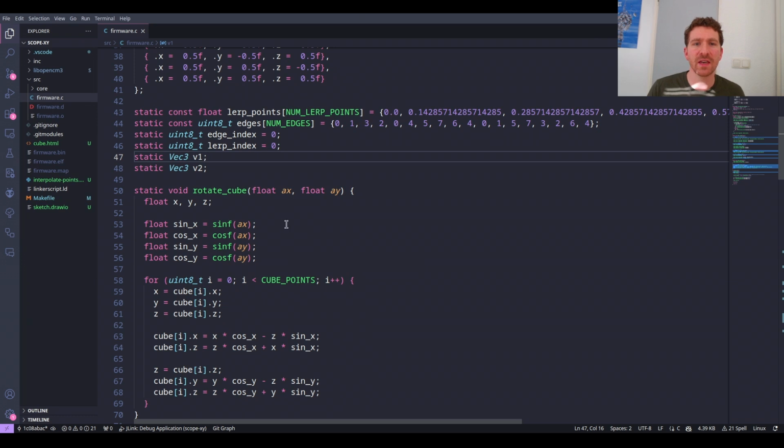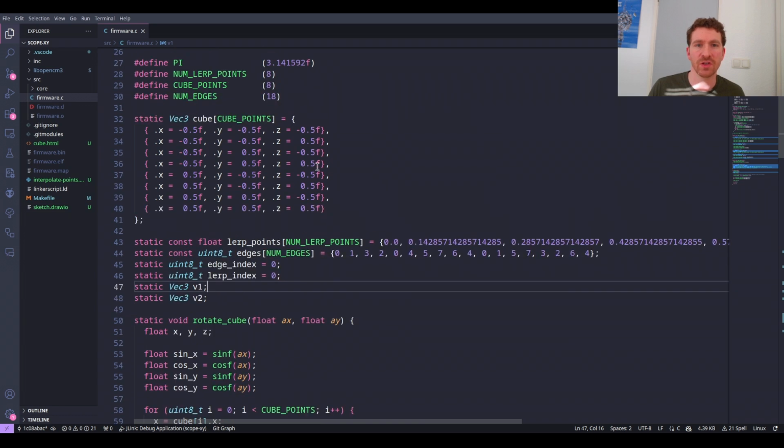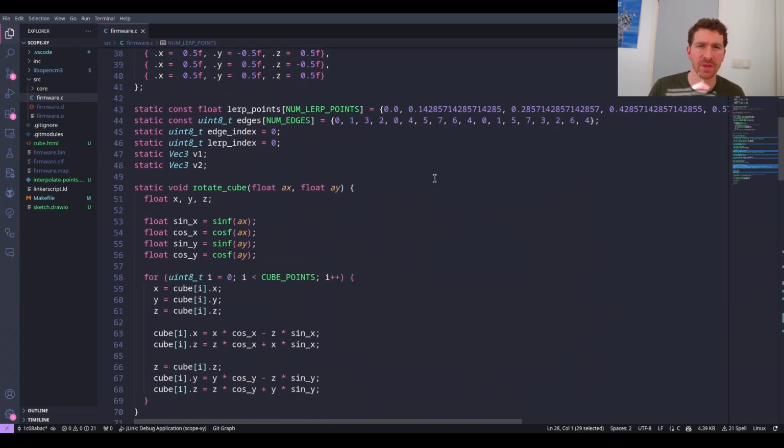Okay, so basically, what we're going to be doing at any given point is just setting our duty cycle to some value. That's what we're doing. And we have to compute all of these in-between points. We need to compute all the points between two edges, and we need to do that with linear interpolation, and we're going to have 8 steps of linear interpolation.